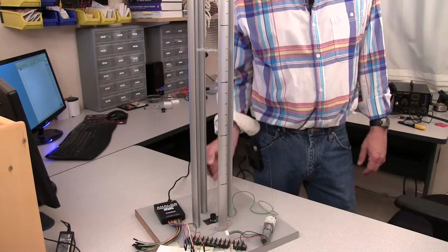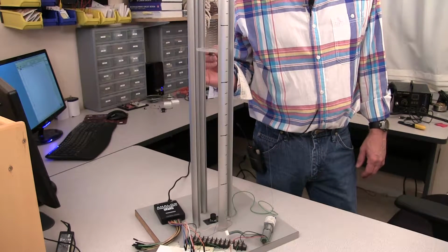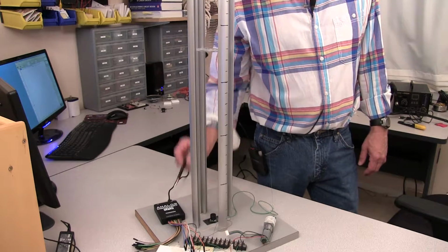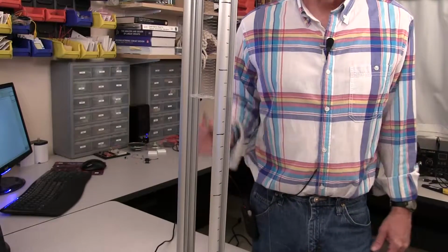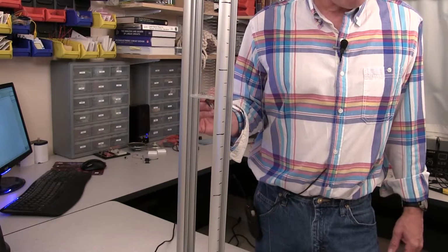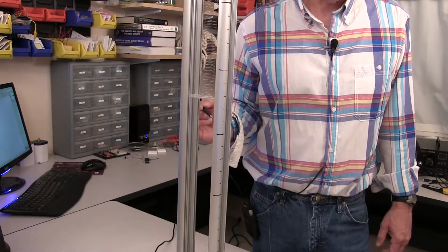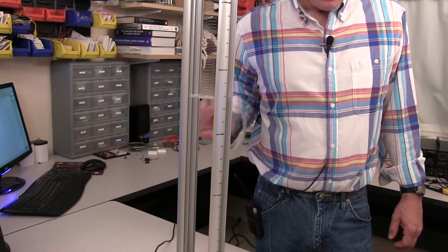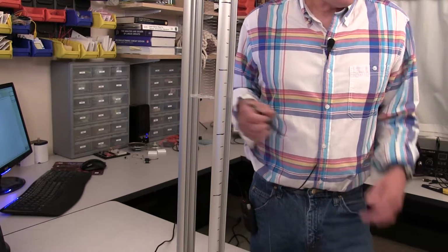This is our system. We're going to use this acoustic proximity sensor to measure the distance to the bottom of this platform. I'll use a USB-based oscilloscope to measure that distance. The sensor will measure the distance to the bottom of this platform. Unfortunately, the sensor is intended to measure a much larger distance than these, so the voltages produced by the sensor will be small. I've connected my USB-based oscilloscope to the sensor to record its output voltage.